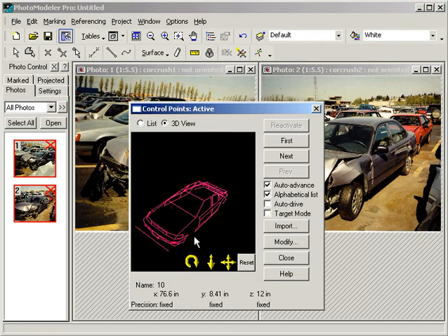This ensured a strong result and therefore a good set of control points, which in turn increases our chances of a good inverse camera result. Control points can also be created using traditional surveying instruments. Any method that can be used to generate an accurate set of 3D coordinates can be used as a source for control points.